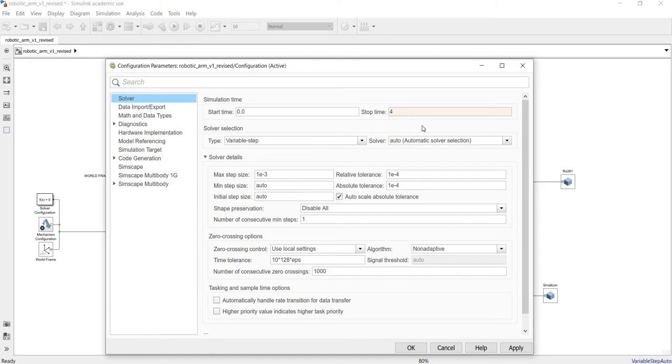The main thing is that if you want to solve the differentials in a specific way, you can set it for your preference, or if the tolerances and the step size are important to you, you can adjust them as well. I do not recommend modifying these options if you do not know what you're doing, because it will greatly affect your computer performance.